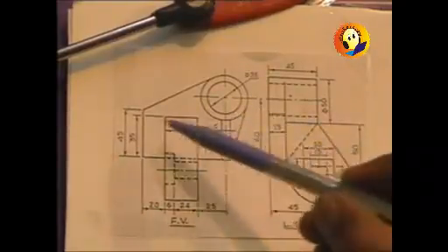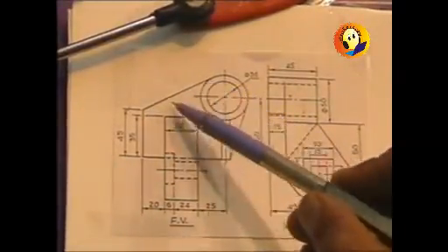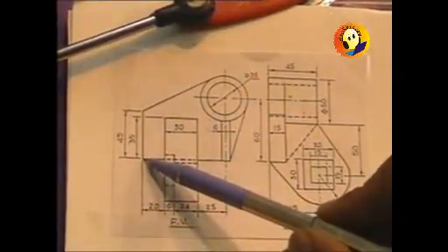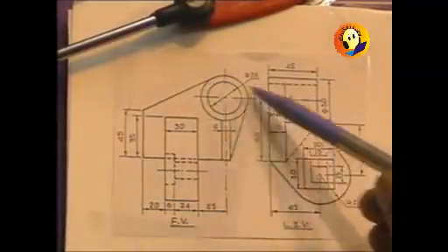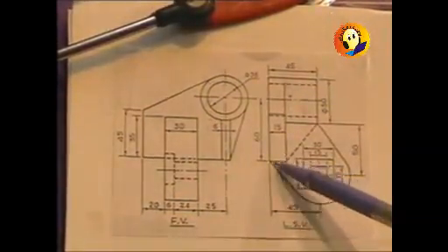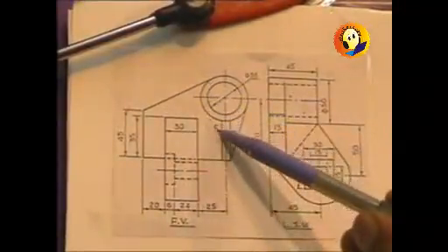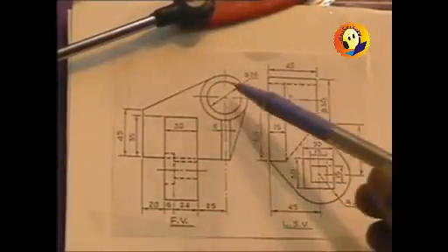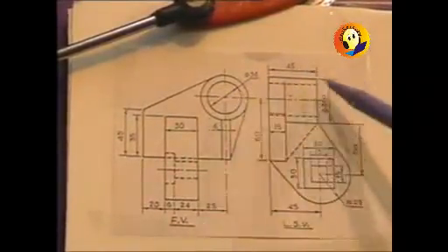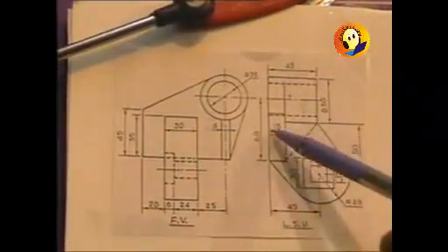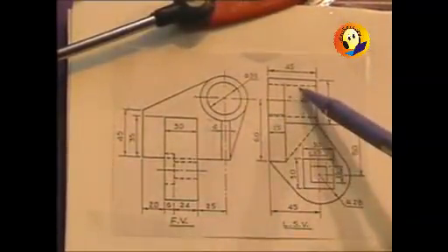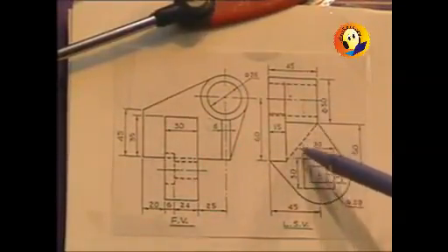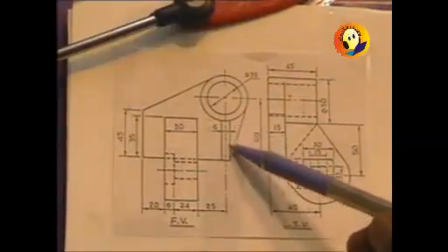We will have to interpret each of these lines correctly. First of all, if I look at this particular inclined line and this particular vertical line, then corresponding to this, going from this point up to this point, if we locate, then we find a line over here, and that means this particular portion should be interpreted as the thickness of 15. So far as these two circles are concerned, we can very well see that it is going to be a cylinder, and this inner circle will obviously be the hole in that particular cylinder. This dotted line over here is actually indicating the rib.